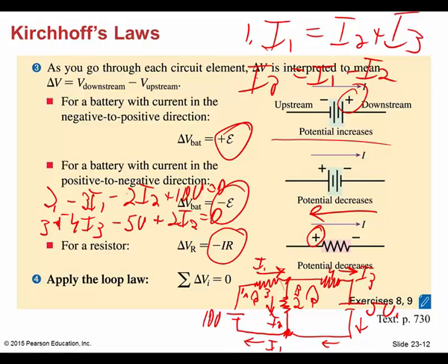Okay, and so then I'd just come right here and I'd substitute I3, and then I'd subtract out my I2s, okay? All right, after you've added them up, what you're going to wind up with is a negative 2I1 minus I2, and a positive 4I2, so you wind up with 6I2 total.